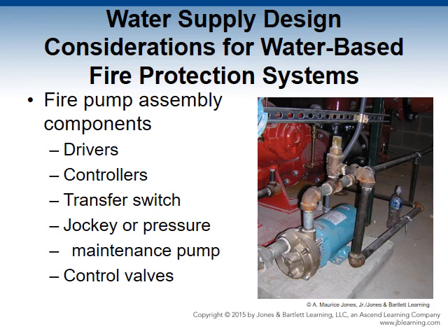Gauges. They are required on the suction and discharge side of a fire pump. They must be at least 3.5 inches in diameter and equipped with a gauge valve to facilitate gauge removal for replacement or calibration.